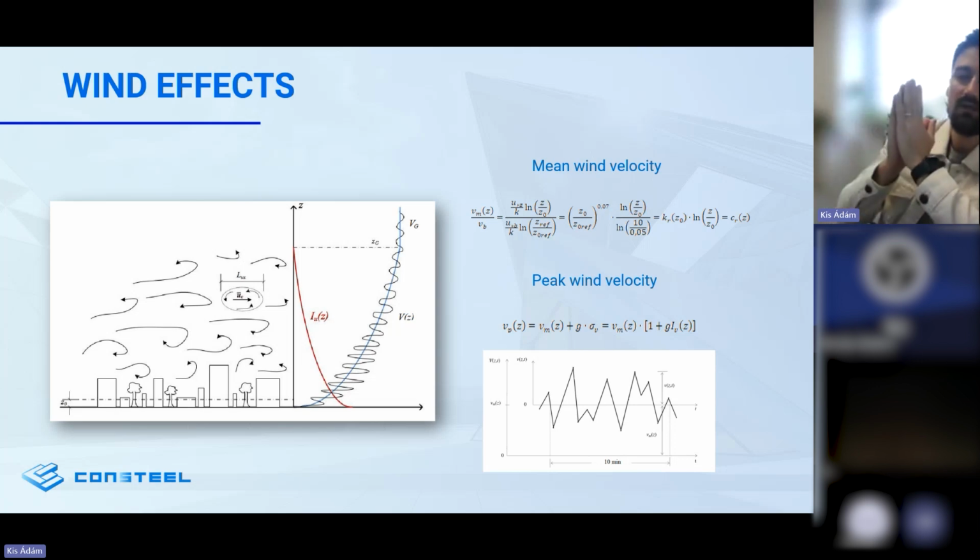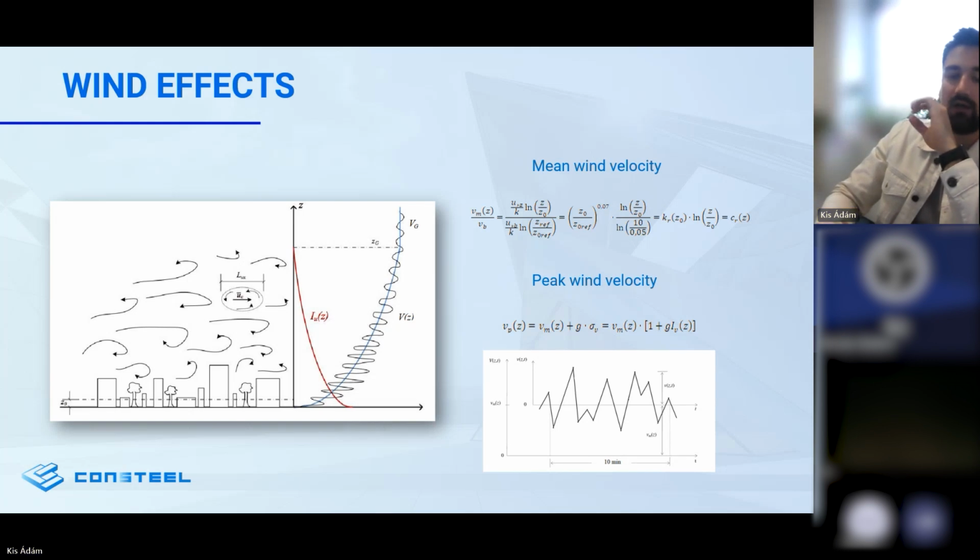One is that turbulence is modeling the natural behavior of the wind. When we have a finite domain where the wind is inserted, or an inlet side where the wind is coming towards our building, we can already take this turbulence term into consideration, based on the obstacles or the actual terrain category.